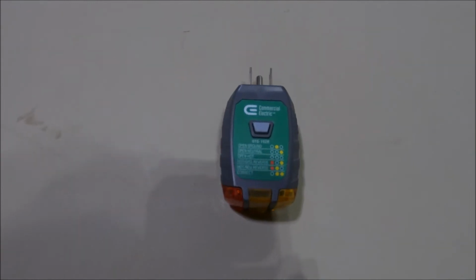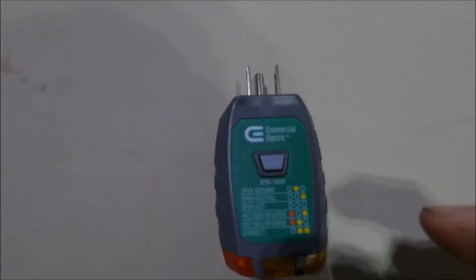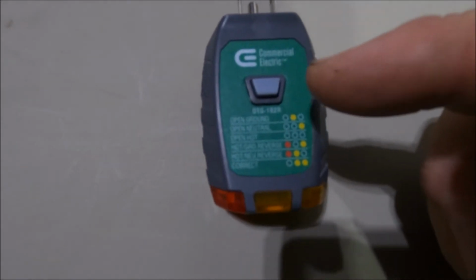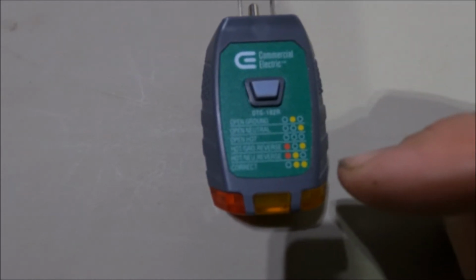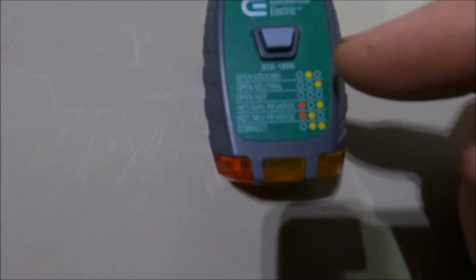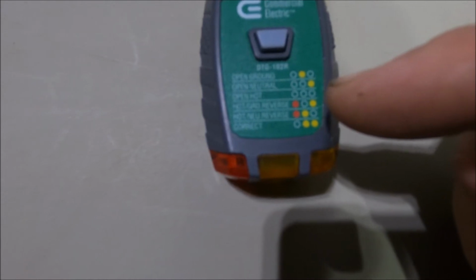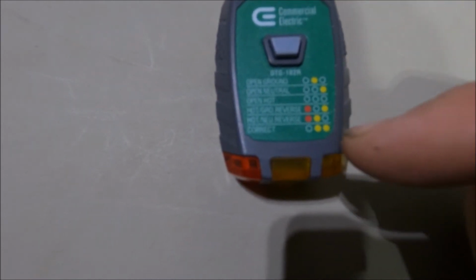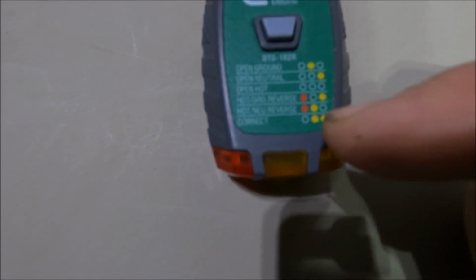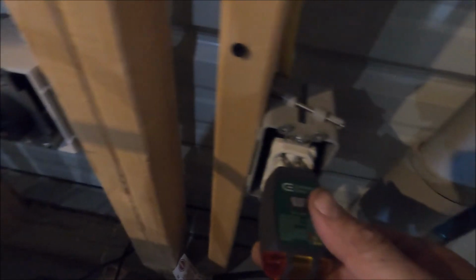The next tool I'd recommend is this plug-in tester. It just plugs into an outlet, and there's a bunch of different codes along here. I'm sorry, my camera's not picking them up. When you plug this in, if there's something wrong, it'll tell you. The first one is open ground, the next one is open neutral, and these different codes will tell you if it's right or wrong. Right down here at the bottom, it's correct if you get the open circle and then the 2 yellow circles. So let's give it a try.